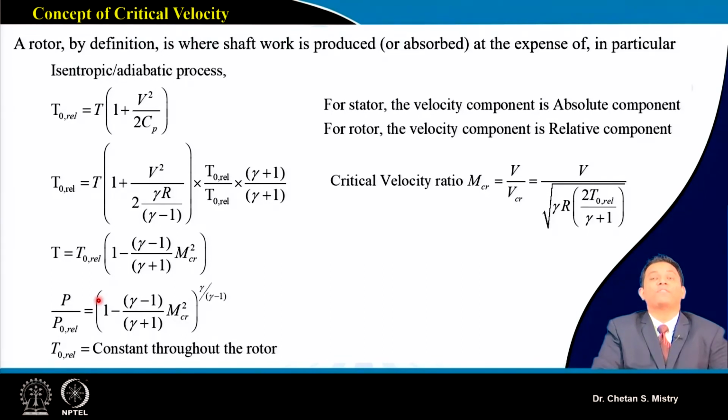Suppose we are not getting it, we make all kinds of modifications in the selection of my pressure ratio, in the modification of my radius ratio and aspect ratio, and so many parameters come into the picture. Once you have done all this calculation based on your computational study, you will come up with the verification that yes, this is what we expected in terms of my pressure rise.